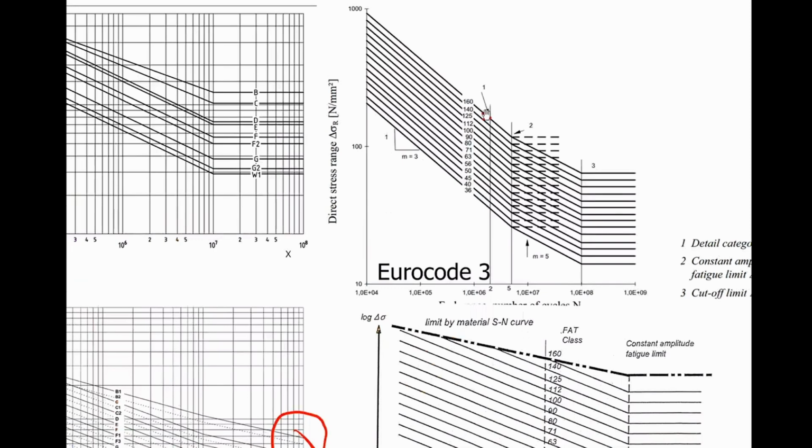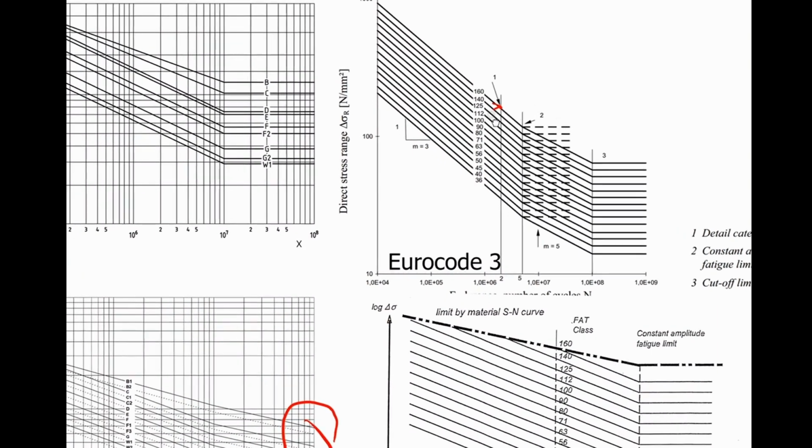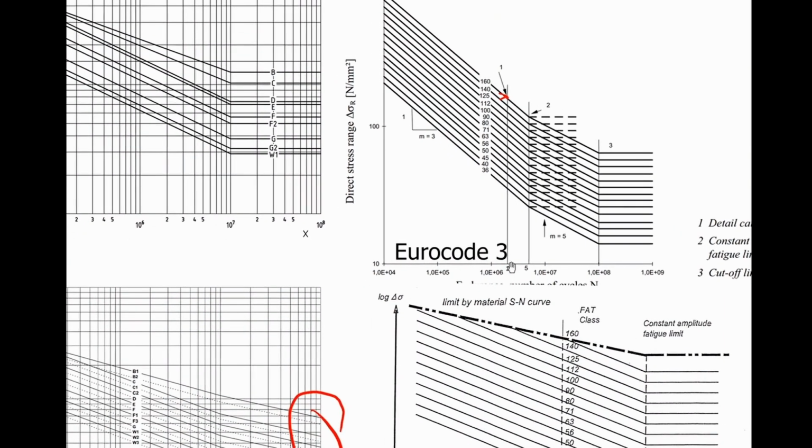If I have here the fatigue stress limit defined at 2 million load cycles because of past tests and measurements, but the slope change is at 5 million load cycles.